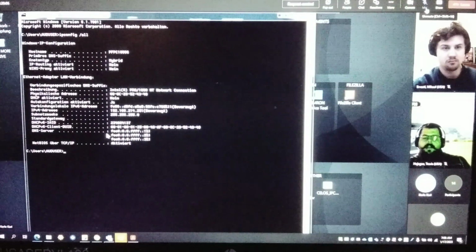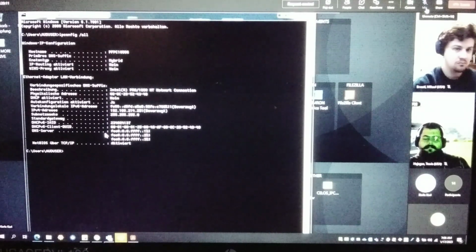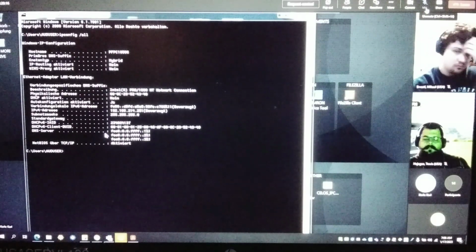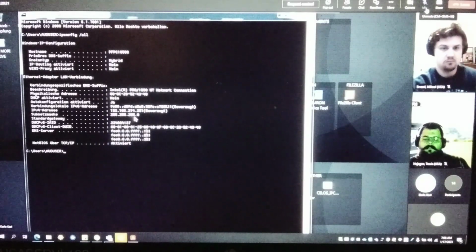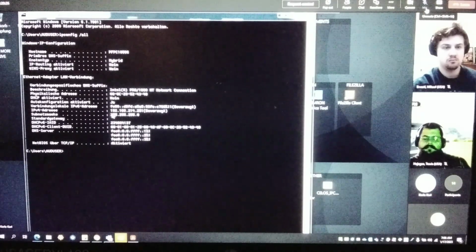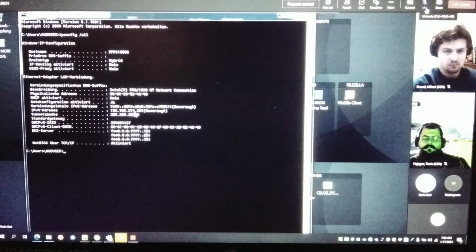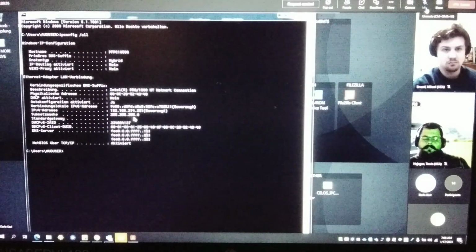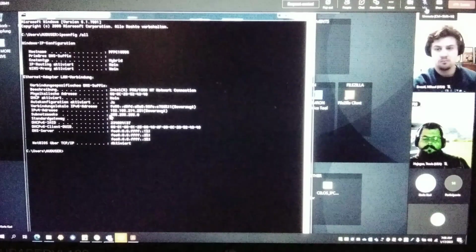Now, when you see that, you know my virtual machine is adjusted to the system network range of the connected machine. Why? Every system network of a numeric control is adjusted to this network range. And the network range consists of the values 192.168.214 and the subnet mask underneath, 3 times 255. This is the network range of this IP address. Why?